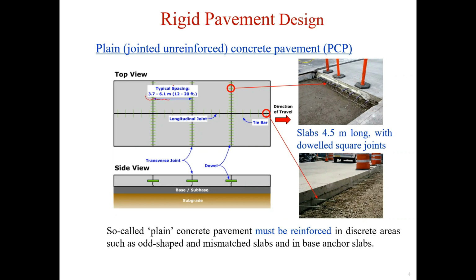In the longitudinal direction, the tie bar is normally used. They are the connectors used for holding faces of rigid slabs in contact to maintain aggregate interlock. Unlike dowel bars, tie bars do not transfer the load, so that's the major difference between them.